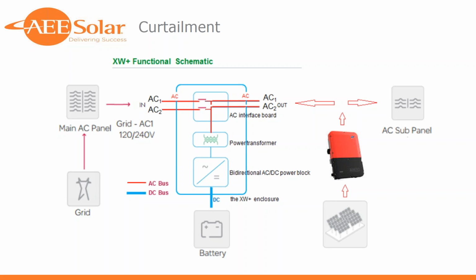So as our application engineers worked with this team, they presented them two options. You can add more battery, which they couldn't do based on the size and the budget they had to work with, or you can have less PV. What they ended up doing was disconnecting one of the PV inverters. They've now got a smaller system and less autonomy, but they've better sized the PV inverter to the battery inverter. The battery would take more time to charge up all the way, but they've done a better job of sizing array to inverter to battery, and they could operate it in steady state at that point.